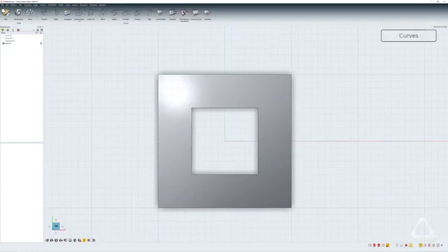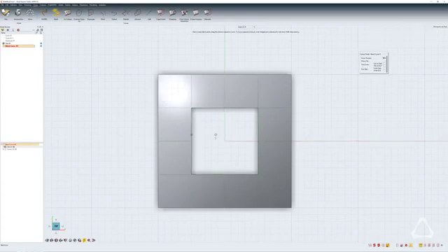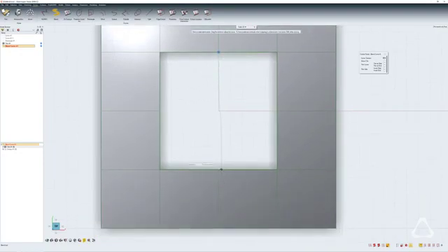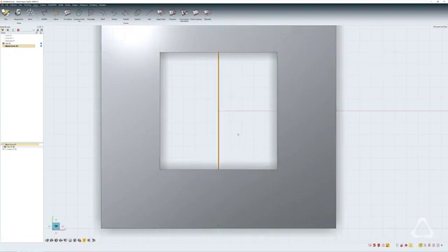You can go to the curves menu and just click on blend. So you don't have to click on a surface. When I move my mouse over the surface, it turns green. So this tells me that I have picked the right surface, and you can just move the mouse along the edge until it snaps to the midpoint. If you don't see the midpoint, just move to the edge until you see an end point, and then come back to the center and the midpoint should be seen. So at this point I can tell that the snap has activated. I just click once and then I move to the other end and then again click once more. So now I have 2 points defined for the blend. I just right click swipe to finish it.